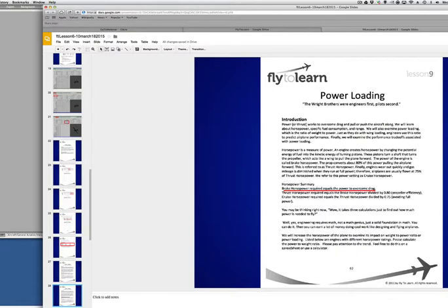They were amazingly efficient. Then the next issue is, you don't want to run any engine full blast all the time. It's hard on the engine, it's hard on fuel consumption, the whole nine yards. So we talk about cruise horsepower, and that needs to be about 75%, 0.75 I should say, thrust horsepower divided by 0.75. So if I have 125 and I really only want to run it at 75% of that, I'm going to need to divide it by 0.75.